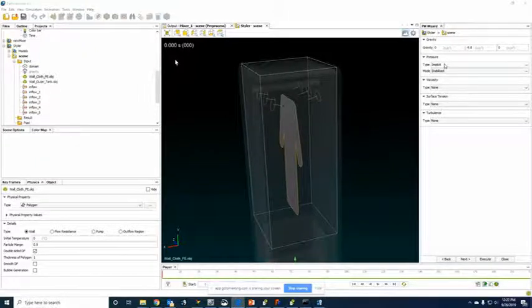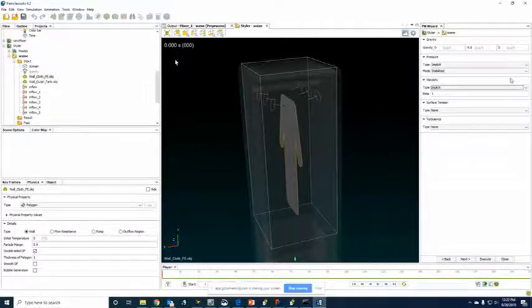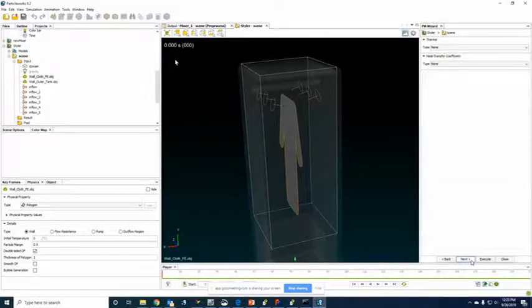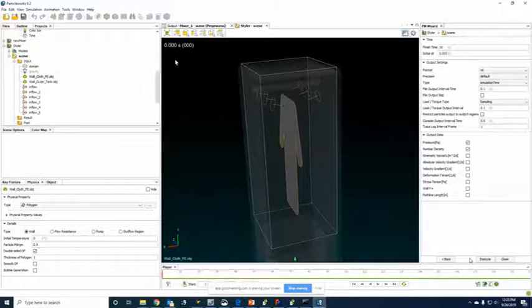We're going to go ahead and leave the pressure model at the implicit stabilized, but we will go ahead and include this viscosity calculation. Go ahead and include an implicit viscosity calculation. We'll leave the rest at default, but you can include surface tension models and turbulence models in that. All right, so we're not going to worry about heat transfer.